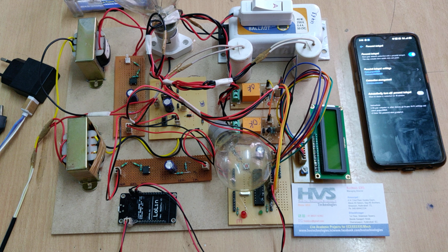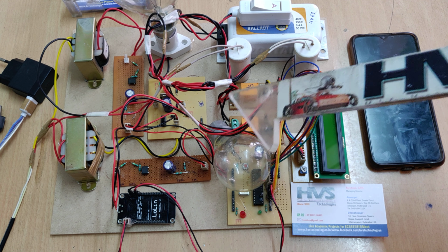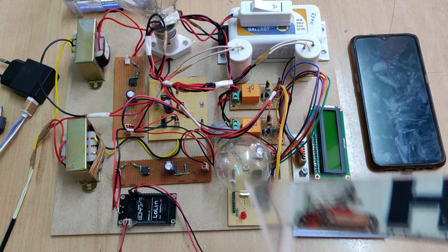With the help of relays, it will switch on one relay first and then check the power factor. If it is corrected above 0.9, then it will leave that, or else it will switch on another relay and the capacitor will continue in parallel with the same R and L load. Then it will check whether the power factor is corrected or not. As we demonstrate in this project with two different loads, one is a 40 watts bulb, another is a 200 watts bulb. Coming to this, these two are the potential divider circuits along with